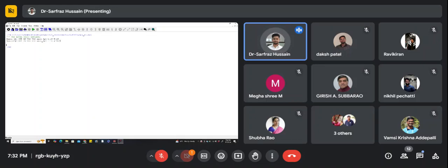Now after we do this circuit, we need to do some simulations, right? For the simulation we need to give some input, and based on the input we'll get some output, right? So let us give the inputs. Here, in the command line, I'll write just the inputs. So VDD, these connections, I am basically giving a netlist.